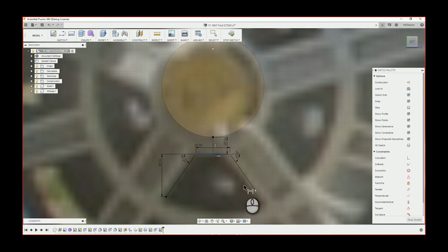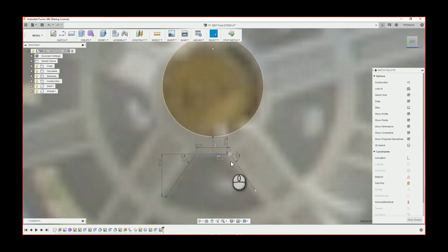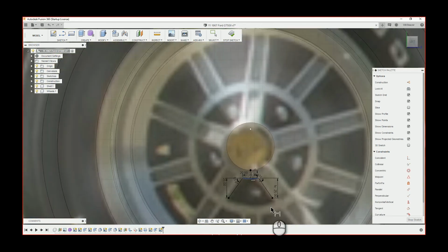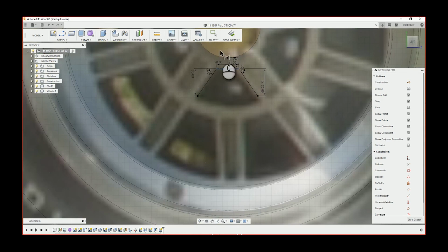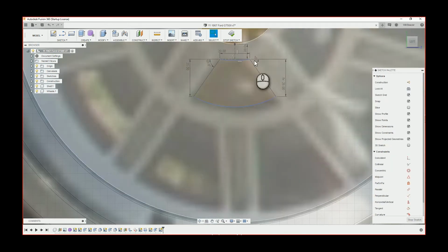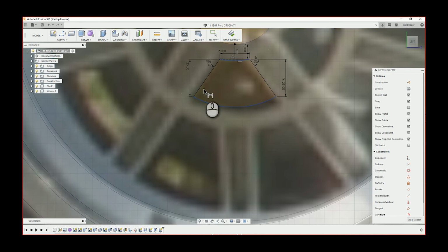And so what I actually do now is, you'll see what I've just spoken about, but with the dimension of the length. I've drawn 25 on the right, and rather than retyping 25 on the other side, look, I just click that dimension and it enters in, and so now they're copied. Whatever I do to that dimension on the left that says 25, it will alter the one on the right. Whereas with the angles, because I didn't do that, I'd have to enter their values separately. So in hindsight, that's just a mistake I made, but yeah.